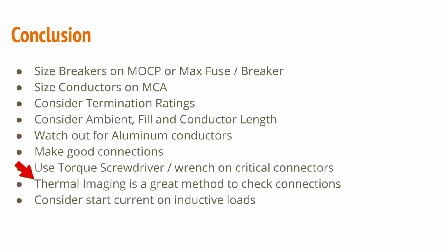Thermal imaging is a great method to check connections under load. Again, thermal imaging doesn't mean anything if it's not at full load, right? It's got to be running at full load, and it's best used as a comparative.